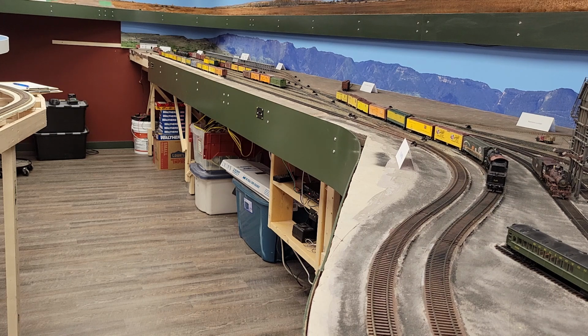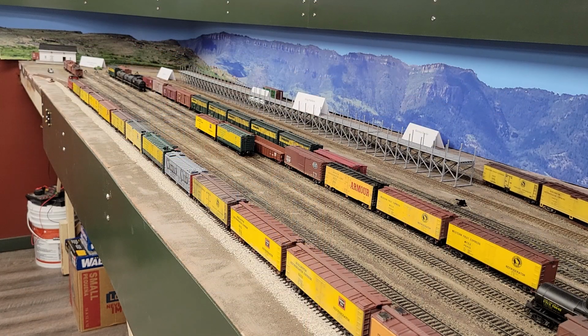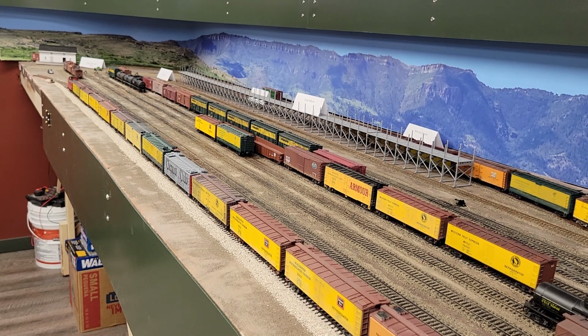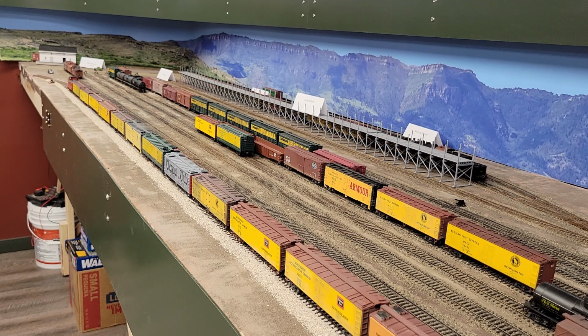The first cut of 8 cars is pulled and moved to the far icing track. Since this train is too long for Casper's relatively short AD track, it stays on the main. This complicates the work of the switch crew by forcing some back and forth moves to get from the main to the icing track, which is off the runaround track. As well as cursing about the car limits on the switchers, the crew also curse the rail engineer who put the mainline switch off the ladder rather than off the runaround track.